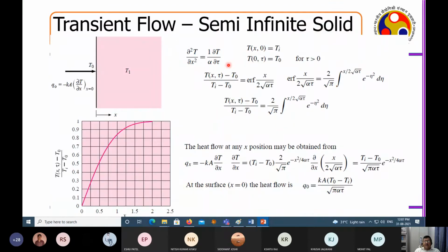Then what we did, we went for a little bit more rather than going for only separation of variables. We solve the problem when you change the boundary condition, right? You can solve the problem in terms of the error function. And we showed that these are more accurate solutions of temperature, right? Say suppose this is T equal to T0 and with respect to X, you may see that temperature is slowly increasing and then saturating in 1.